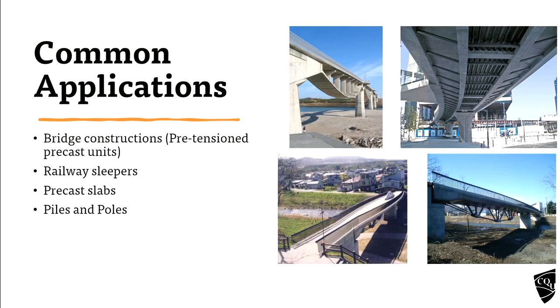So if you want to put the bridge across the river, if it is RC beam, you may need to put a couple of columns inside or within that river, because we can't have longer spans. But this one can go longer spans. Sometimes we don't have any middle columns, or maybe fewer middle columns, depending on the width of the river and others. So we should be able to look at the longer spans.